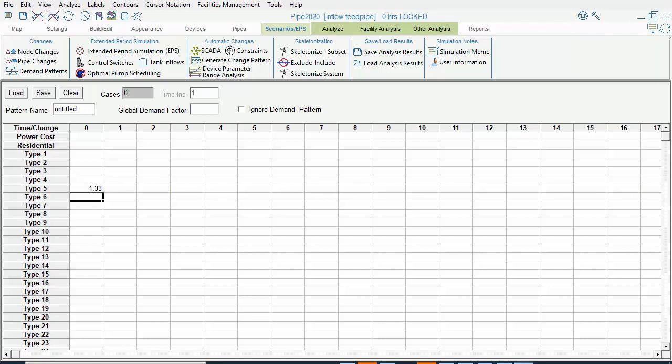This convention allows users to set up a flow multiplier which doesn't change without having to enter multiple values. If the first column is left blank, the field is treated as if it contained the number 1, and thus all values are set equal to 1. However, this only applies if the column is blank. Any value we enter into this table is carried forward until it's changed.